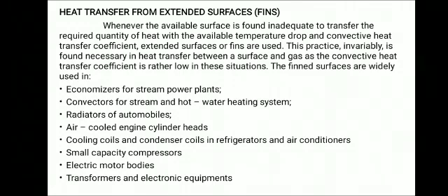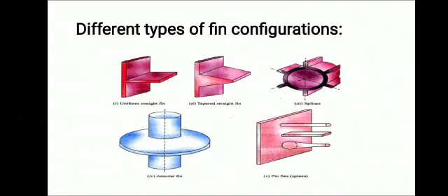Heat transfer from extended surface. Fins: whenever the available surface is found inadequate to transfer the required quantity of heat with available temperature drop and convective heat transfer coefficient, extended fins are used. Fins are used in economizers for steam power plants, radiators of automobiles, air-cooled engine cylinder heads, small capacity compressors, electric motor bodies, transformers, and electronic equipment. These are the different types of fin configurations.